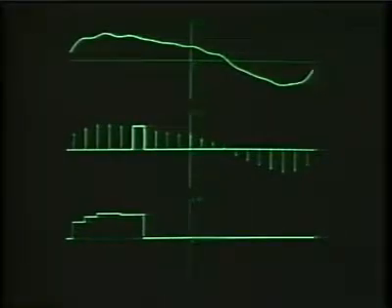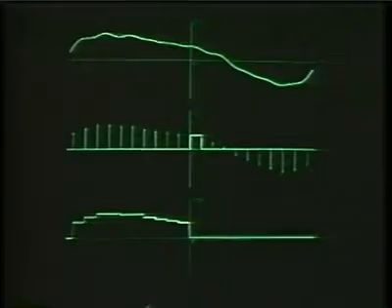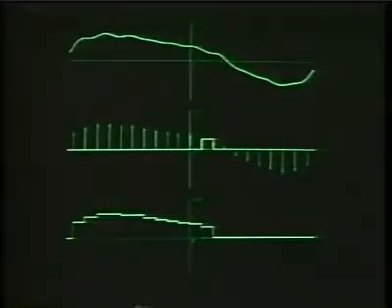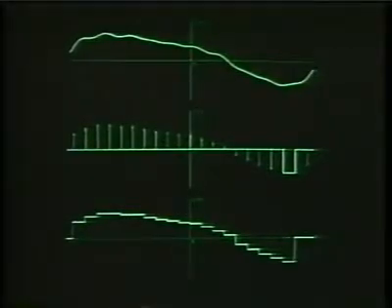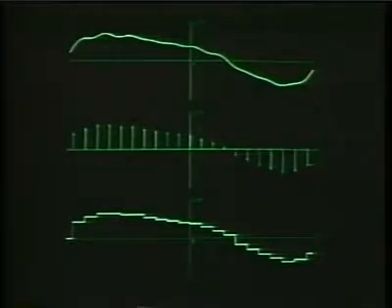And notice in this case, as in the previous case, that what we're basically watching dynamically is the convolution of the impulse train of samples with the impulse response of the interpolating filter, which in this particular case is just a rectangular pulse. And so this staircase approximation that we're generating is the zero-order hold interpolation between the samples of the band-limited signal, which is at the top.